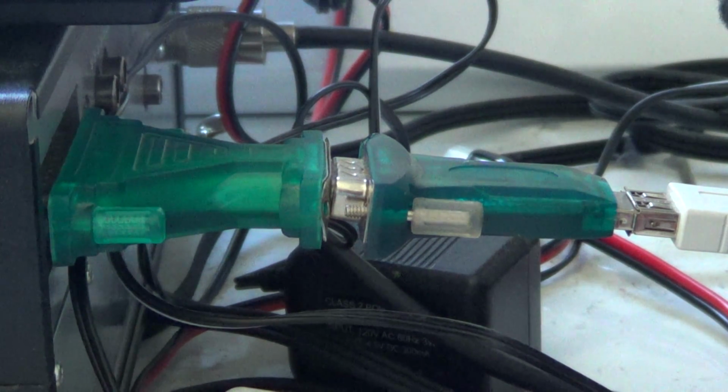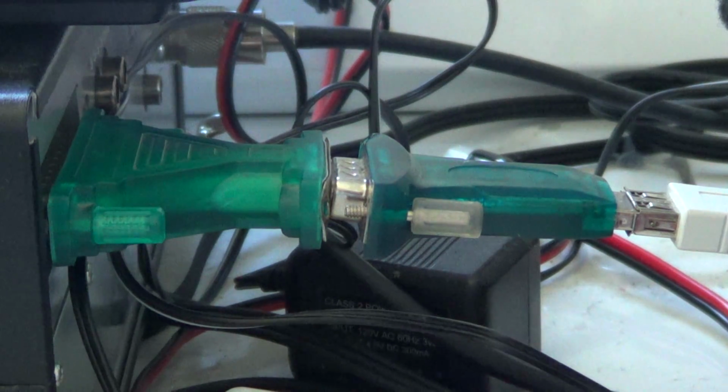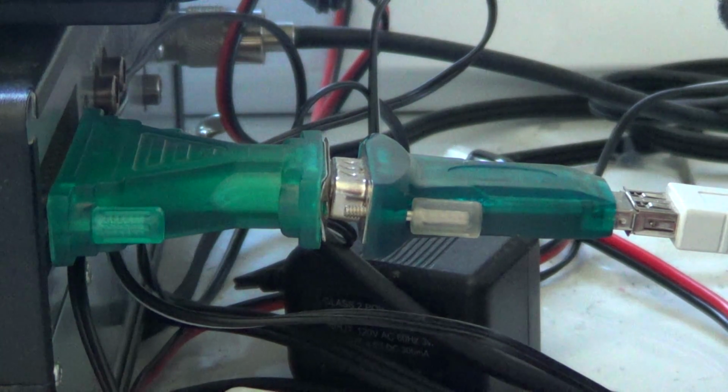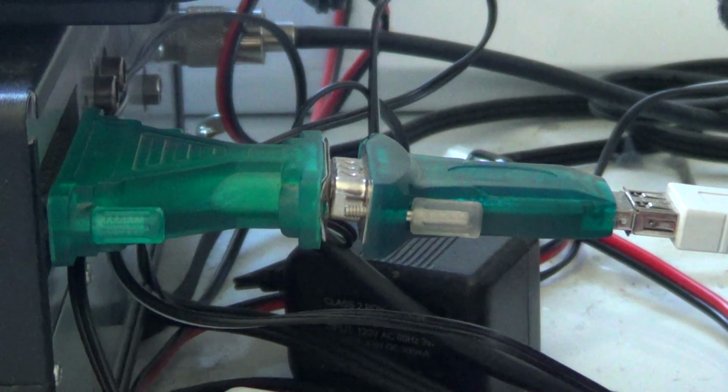Maybe you've looked at the other videos on how to hook up your radio to your computer. Once everything is done, what you actually need to check is some information, because either you have, like me, that USB to serial adapter, or maybe you already have a COM port in your computer. Basically these ports have settings and they have to match correctly to communicate together. One of the biggest problems people have when they try to use their computer and the radio is a mismatch of the communications information.